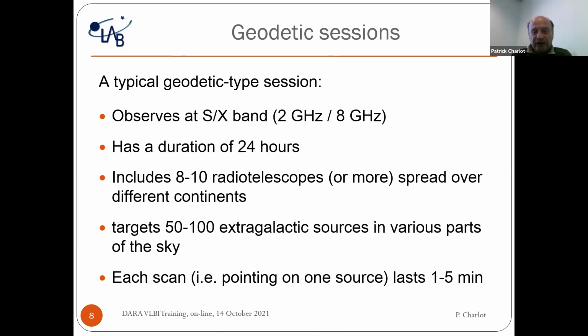And we do this because these are simultaneous observations, in order to eliminate the effect of the ionosphere, because the ionosphere perturbs the measurements. Using a linear combination of the quantities at the two bands, we can eliminate the ionospheric effects, and I will say more about that in the modeling part.